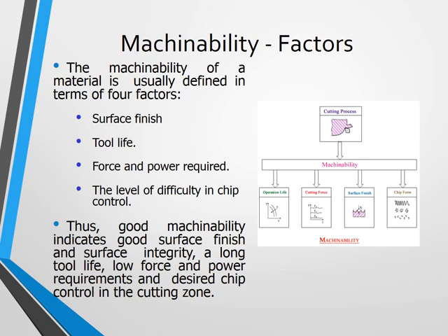Thus, we can say good machinability indicates good surface finish and better surface integrity, a long tool life, and also low force and power requirement and desired chip control in the cutting zone. If all these things are there, we'll say that this material exhibits good machinability.